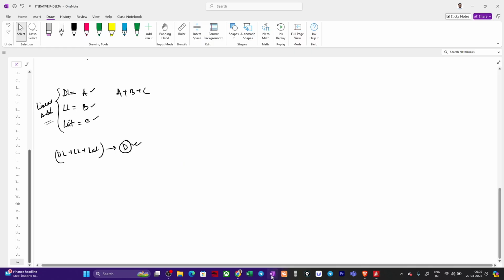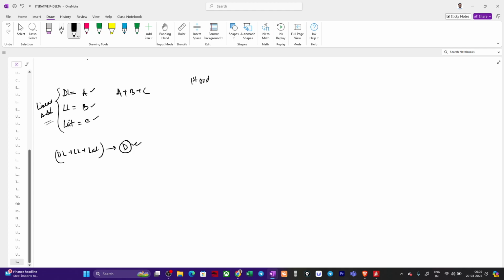So I will just write it here from the first model, the normal general model, or you can say first order linear analysis. We got delta max equal to 55.855 mm. Though it is very high, because I have just taken a general sizing of column, a very small size.